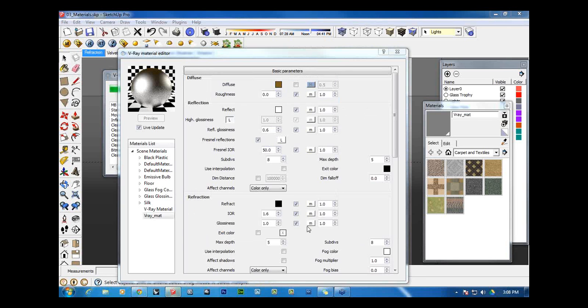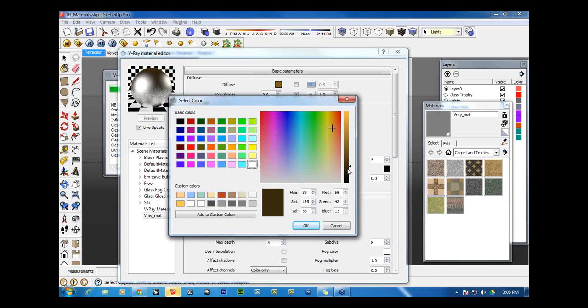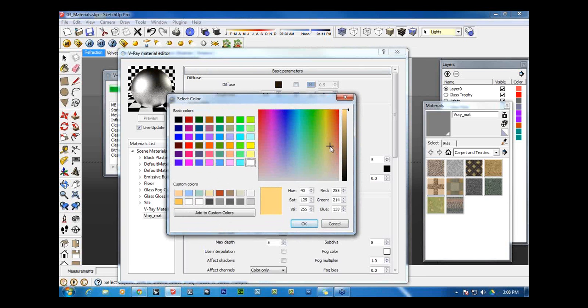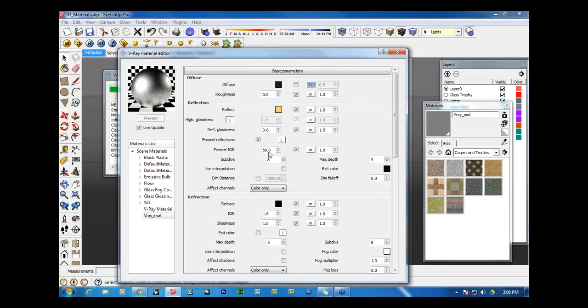If you want to create gold material, for example, let's go back to a dark brown color for the diffuse, and I'm going to change the reflections to kind of yellowish, depending on the color of the gold that you want. And let me increase the blurriness or the glossiness. Now this is the gold material. You could create a render.